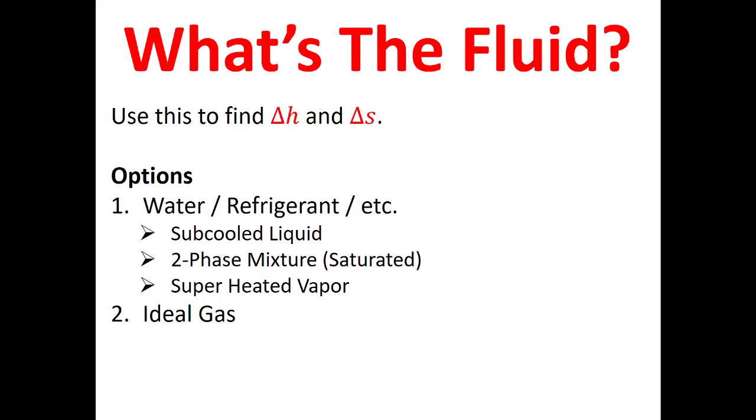In this case, the fluid is going to be a refrigerant. Now, because this refrigerant is moving back and forth across the vapor dome, because it's evaporating and condensing, we'll fix states in a similar way to how we would for a Rankine cycle. But we learned a new way to fix states for these refrigeration cycles graphically using a P-h diagram.